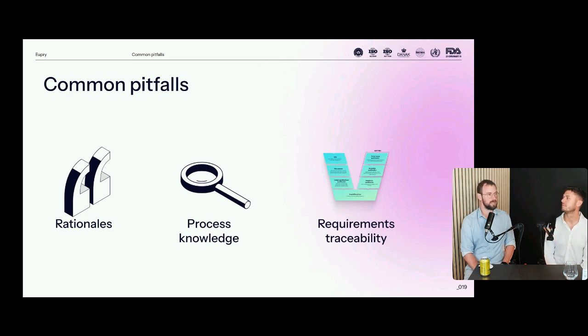Well, the risk is that there might be airflow issues. The guidelines are actually quite well described on this topic, but the risk is that when you start filling in products, airflows might be disrupted, which means that temperature distribution might be uneven or might create areas of colder air and hotter air, or whatever.